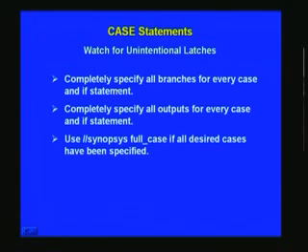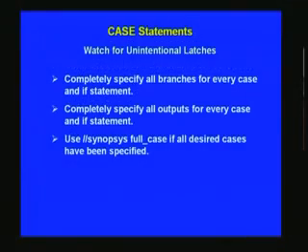The synthesis tool itself won't permit you to go beyond. And even if you wade through all the tools, finally when you make the chip, you will see that it doesn't work when you hook up the circuit. Or it may still work, and years later, when it has reached the customer and has been functioning, and you have changed the technology in the meanwhile, then it may malfunction. For example, the time dependent delays which we have covered earlier will be detrimental here.